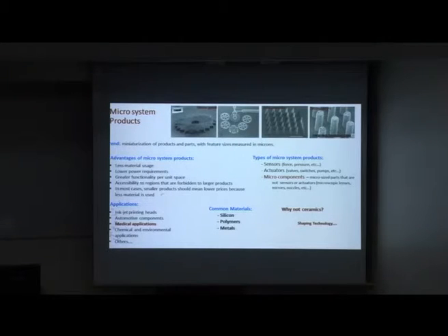Now the question could be, why not ceramics? Among several reasons, one could be the shaping technology. If you think about the size of these things, lower than 1 millimeter, it's difficult to find a technology able to produce these micro things at a reasonable price with high final quality without the need of machining the microcomponent.